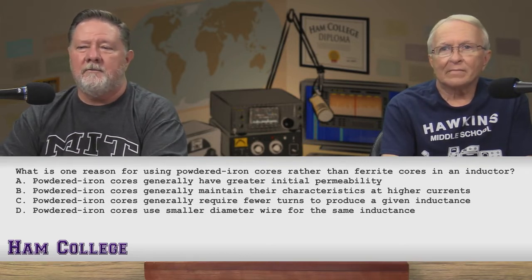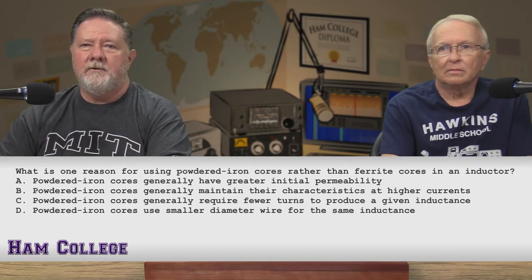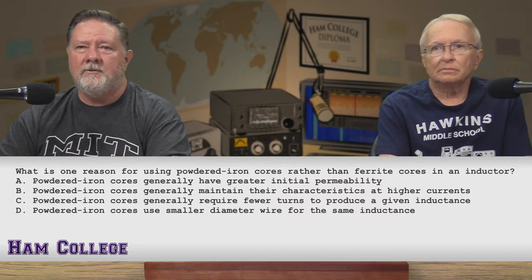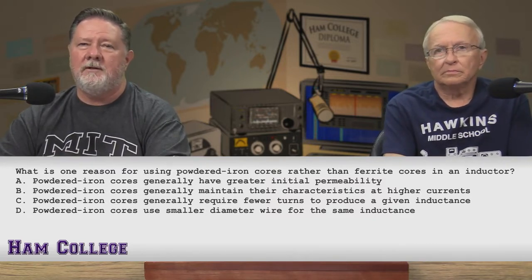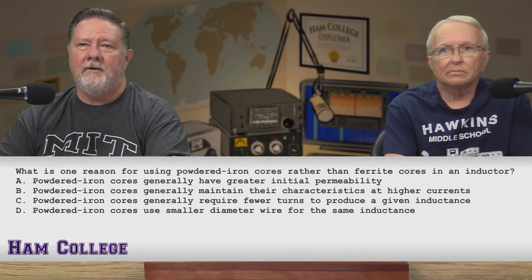Okay, so let's go through this process of elimination here. The reason for using powdered iron cores rather than ferrite cores. A, powdered iron cores generally have greater initial permeability. Well, that's false because we established in a couple of questions back that ferrite cores do.